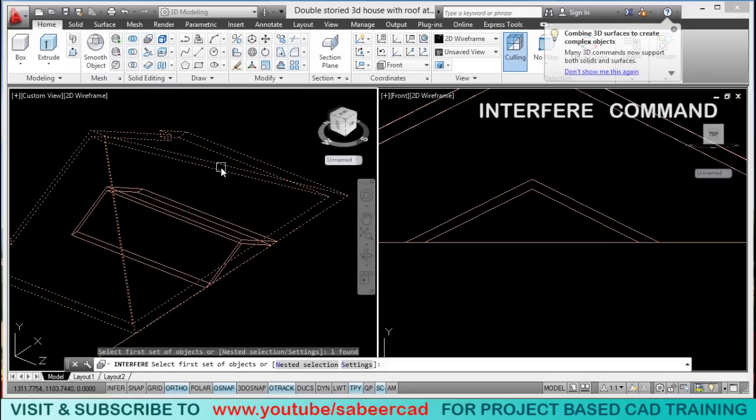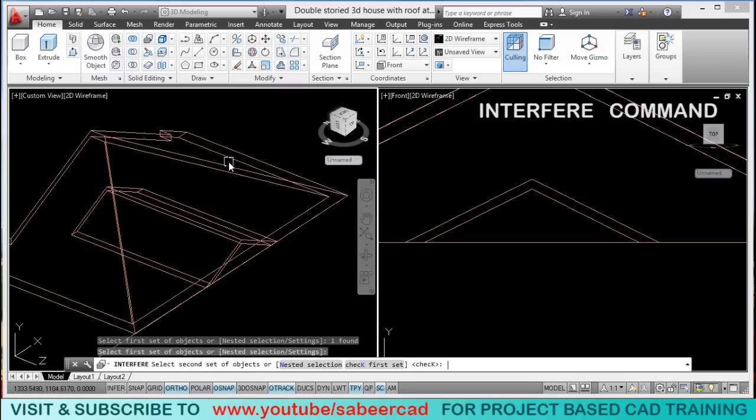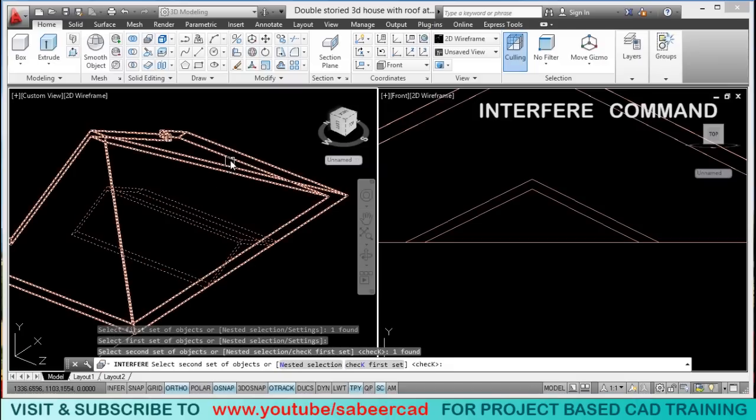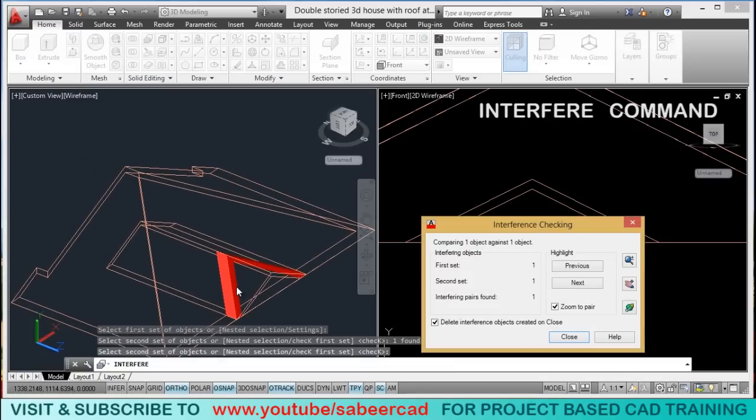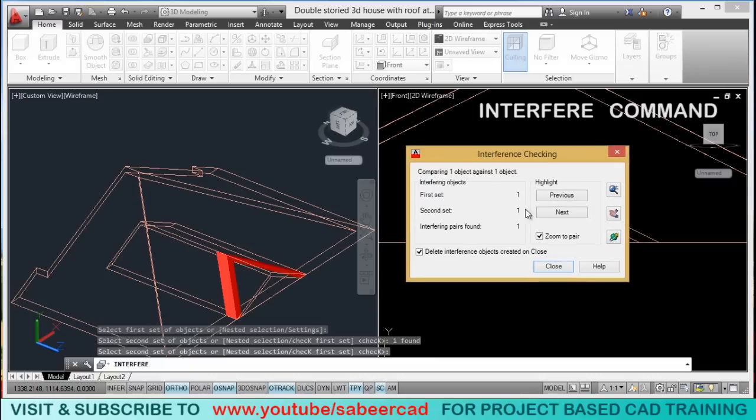You are supposed to select the first set of solids, and this is the first set of solids, and you have to give an enter, and that enter is important. Just give an enter and select the second set of solids and give another enter. AutoCAD shows the overlapping area in red color, and it will show you the two sets of solids here.